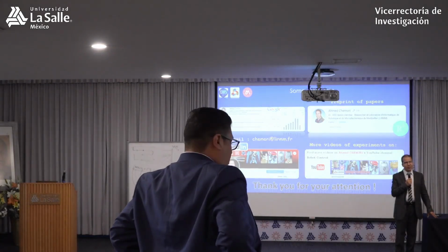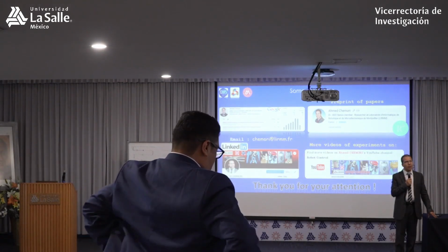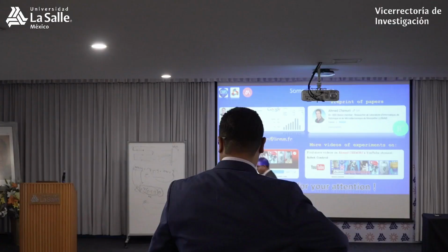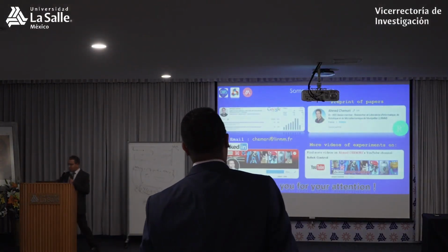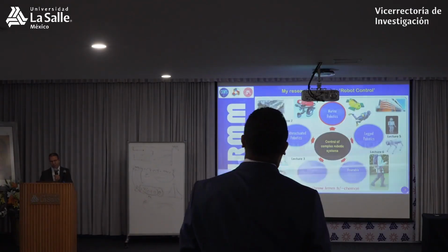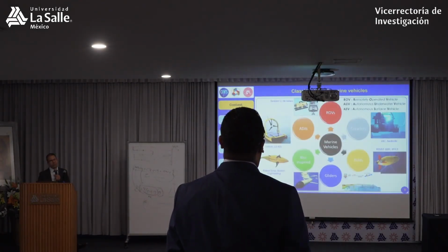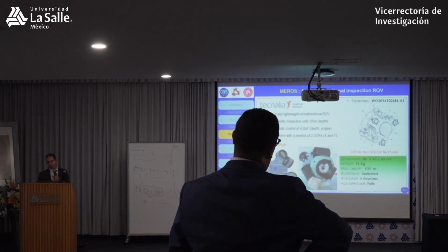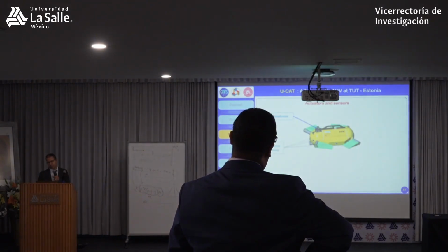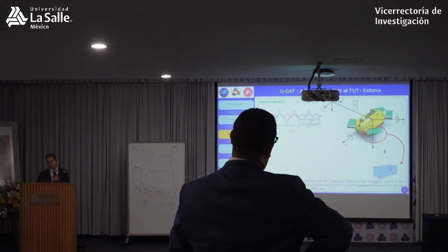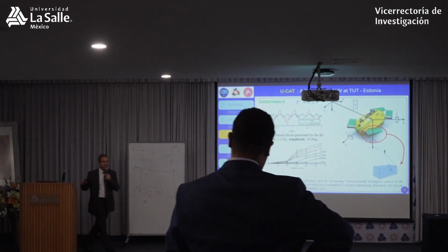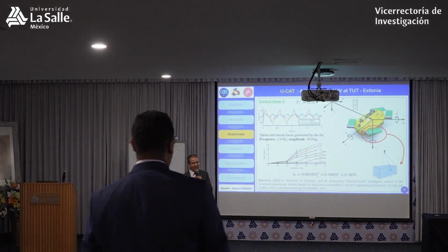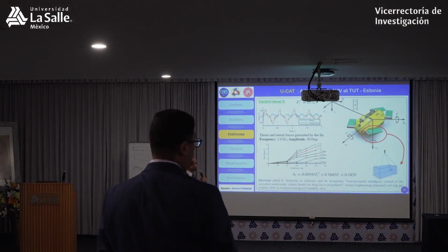I was wondering about the approximation functions that you made. I think in slide 28, you presented the function about the estimation of the amplitude that you had to make with the actuators. So the question is, especially for this type of vehicles, how sensitive are the modeling errors that could occur, for example, in this quadratic function that you used to estimate it? Because there are a lot of cases that depend on the frequency and the propulsion.